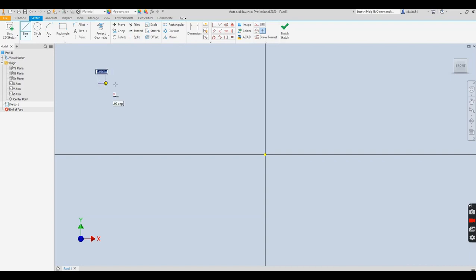Now I'm going to draw a line and go straight across, and notice that if I keep that line straight, it not only looks straight, it's not ragged like that. You'll also see a little symbol there, and that tells us that it is horizontal, so it is going along the x-axis right now. If I make it straight across, you almost feel it snap into place. I click on it, and you'll see I've got 0 degrees, and again you'll see the icon for horizontal.